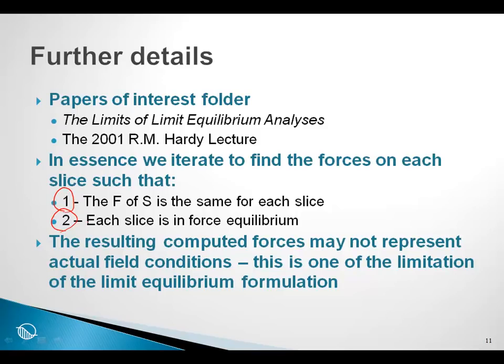The side effect of doing this is that the resulting computed forces may not represent actual field conditions. This is one of the limitations of the limit equilibrium formulation. Fortunately, this does not invalidate the factors of safety that we compute, as we will see at the end of this session.